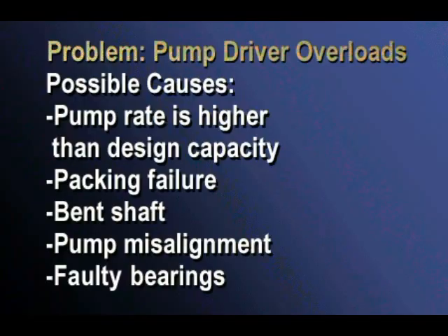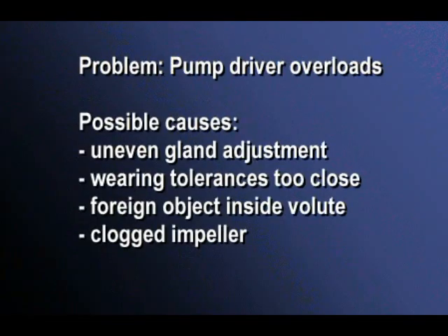Problem: pump overheats and kicks out because of overload of the driver. Possible causes: pumping is over capacity because the existing head is lower than the rated head. Packing is too tight or is defective. The shaft is bent. There is misalignment. Bearings are faulty. Uneven gland adjustment. Wearing ring tolerances too close. Foreign object inside volute. Clogged impeller.